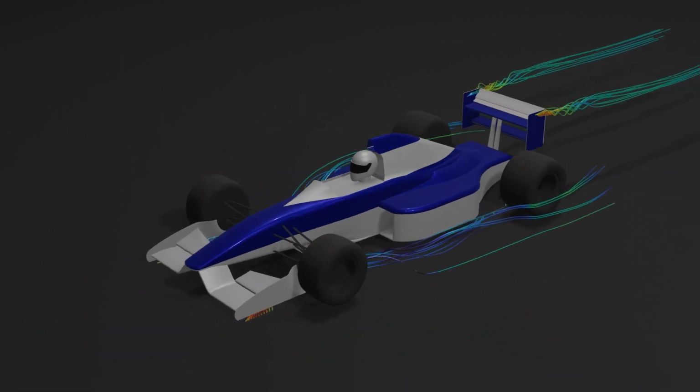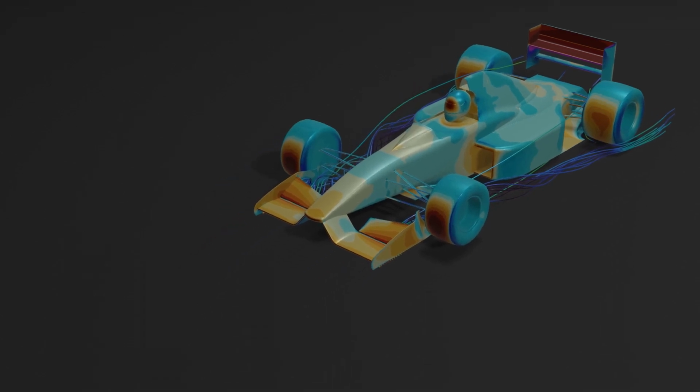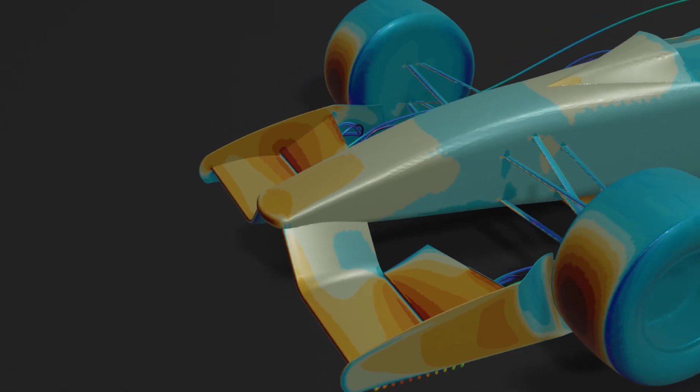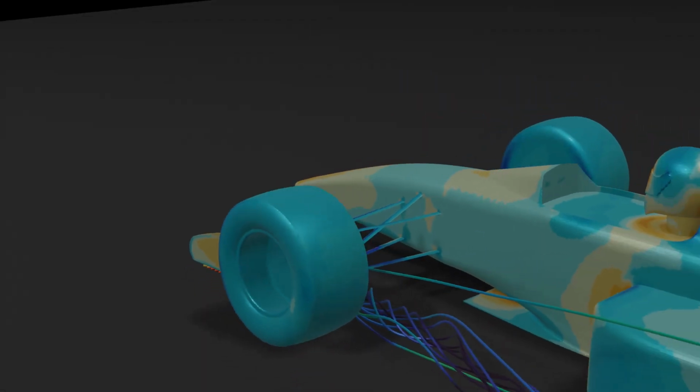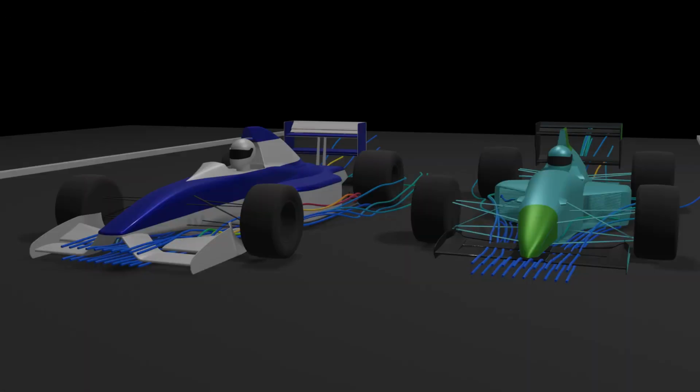So these simplified wheels are rotating, but obviously not generating nearly as much turbulence as they would otherwise. But then there aren't brake ducts and brakes and so on. Though saying this, another model I simulated, the March 88-1, had wheels contributing more than 40% of the drag, and these are the same wheels. But then the 88-1 was a much more efficient car generally. In the real world, it produced an efficiency above 3 anyway.